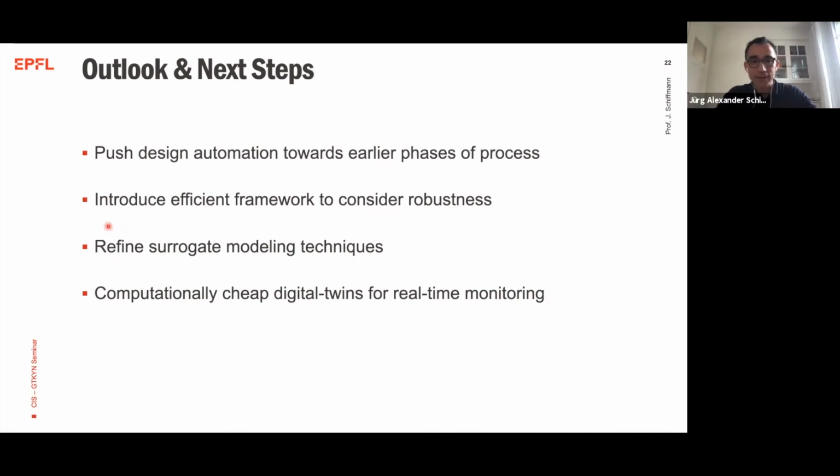What has also been identified for this gearbox and electronic actuator problem is the robustness of solutions with regard to manufacturing deviation. It is a very important topic, because if you can manufacture parts with a large tolerance, this also decreases cost. If you can find a solution that is very robust towards manufacturing deviation in terms of performance, that is very beneficial also for the cost of the system. Now, robustness calls for even faster models, so we are certainly going to work on surrogate modeling techniques.